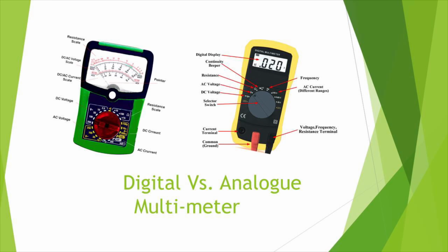An analog meter is much faster and easily capable of reading a signal at 50 times per second. However, due to the inertia of the meter needle, the reading will not be of great accuracy. If the signal changes faster than this, then an oscilloscope is required.